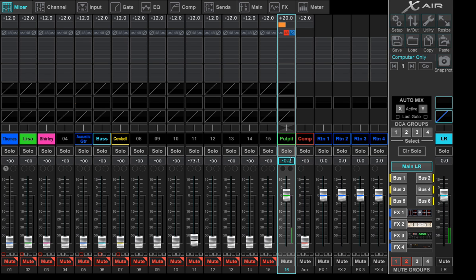And you want to begin with all of your channels that way because that makes it common all the way across for the sliders. And then you want to adjust the gain to be appropriate to 0 on the slider. So the slider is there to make fine artistic adjustments during the course of the service. So generally you would start with the gain down at 0. But I can't really do that because then you won't hear me anymore.